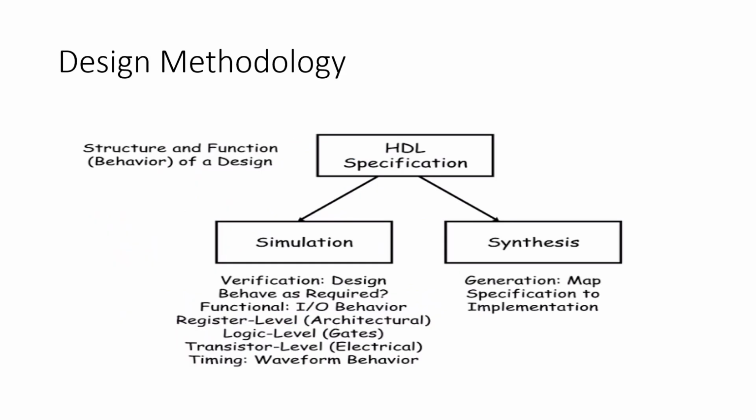Let me explain the design methodology we're going to follow in HDL. Digital circuits are generally designed in the following steps. The first step is the specification, which defines the problem. The next step is the design. Design means we have to choose the design method, whether it be behavioral, data flow, or structural.